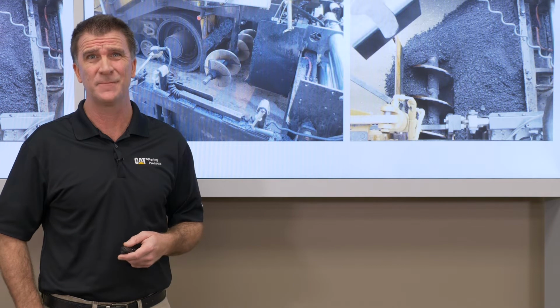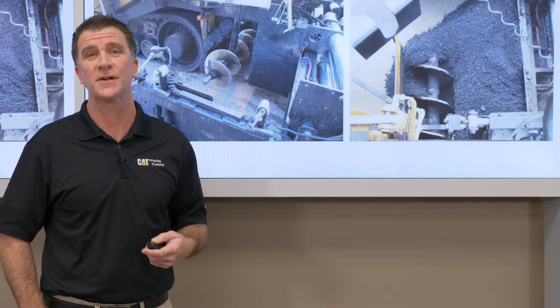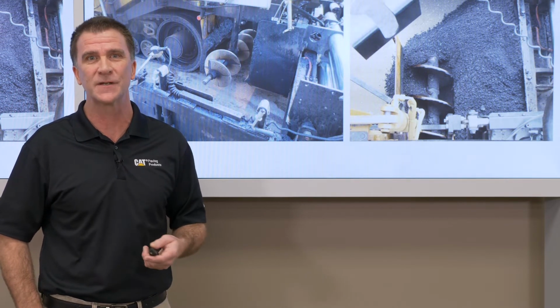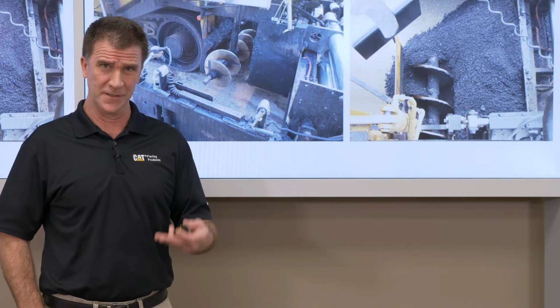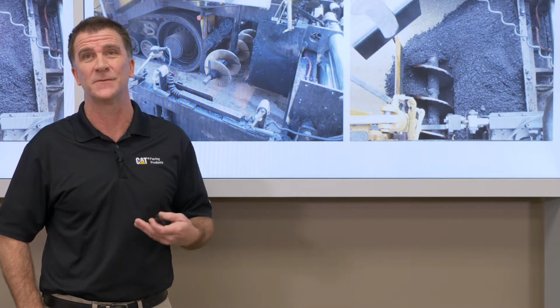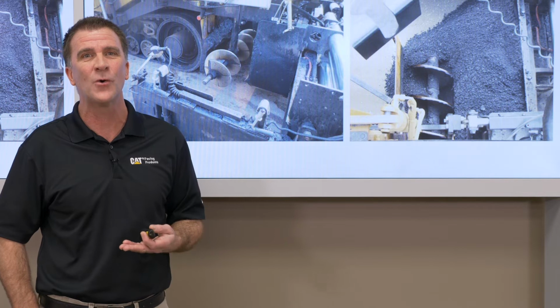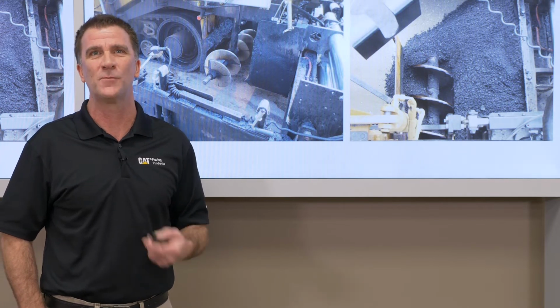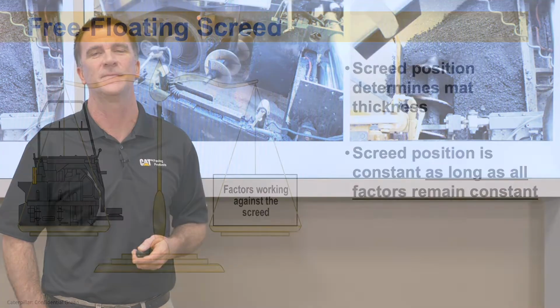But because they're carrying more mix, they also tend to be generally a little more forgiving in terms of variability in the feed system. So if your mix runs a little high or a little low, a rear mount screed is a little more forgiving in that regard.